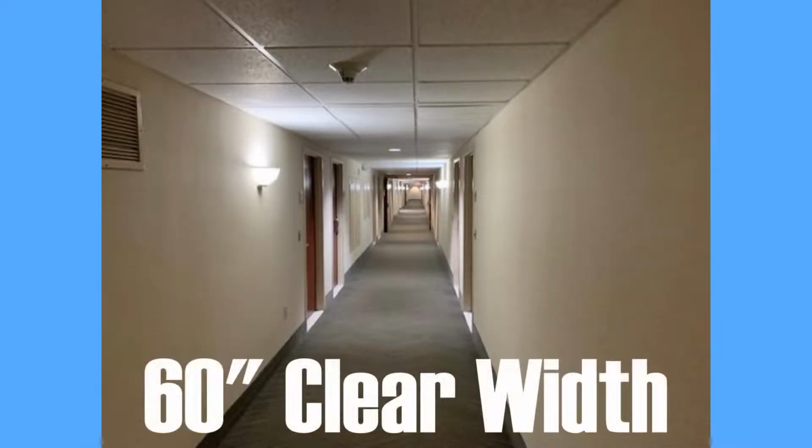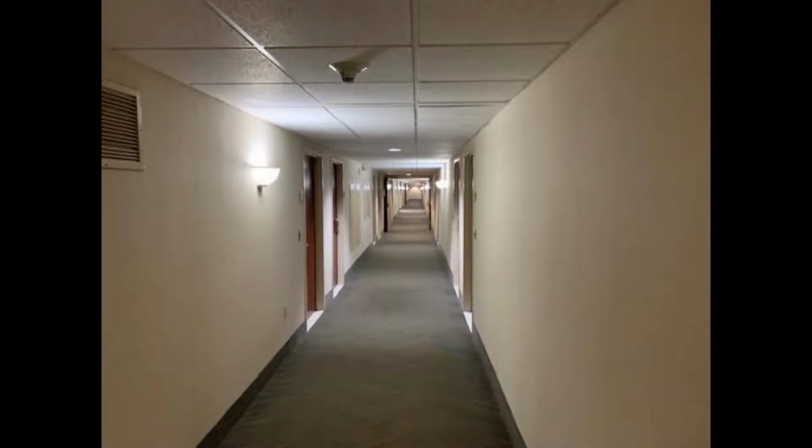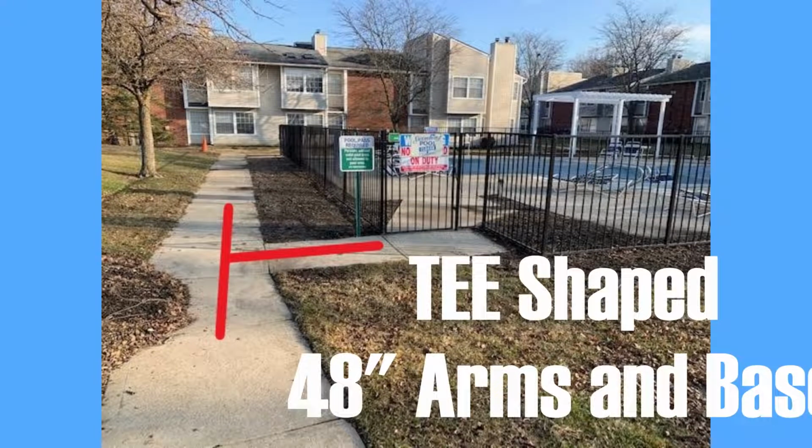An accessible route with a clear width less than 60 inches shall provide a passing space every 200 feet. The passing space shall be either a 60-inch by 60-inch area or the intersection of two walking surfaces, providing a T-shaped turn with 48-inch minimum arms.